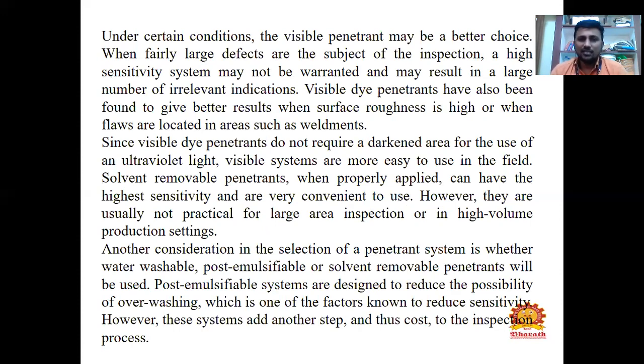Since the visible dye penetrants do not require a darkened area for the use of an ultraviolet light, visible systems are easier to use in the field. Solvent removal penetrants, when properly applied, can have the highest sensitivity and are very convenient to use. However, they are usually not practical for large area inspection or high volume production settings.